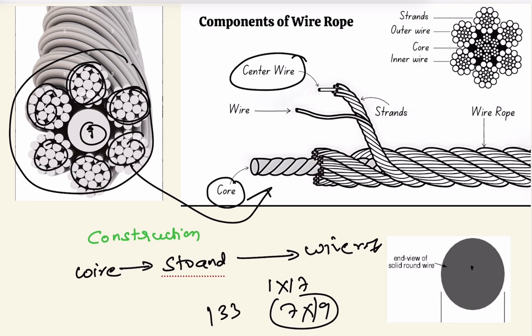Now, what happens basically from the wire rope construction, as many small wires with frictional contacts are there. In it, there is a center wire. Around the center wire, there are a number of wires twisting around each other. So basically, there are many small wires with frictional contact, which allows slippage and deformation.